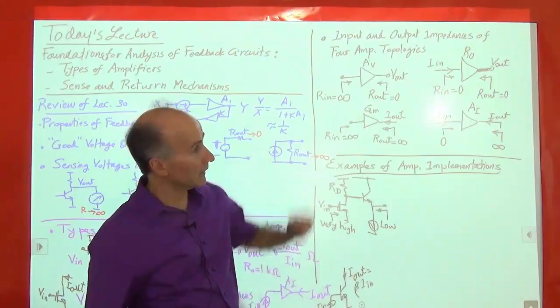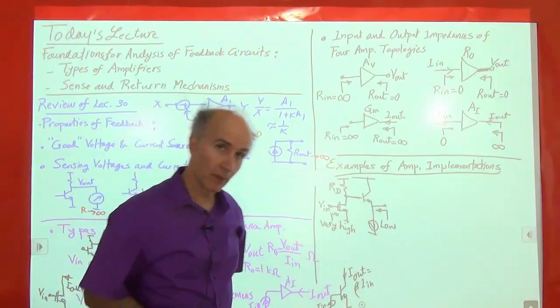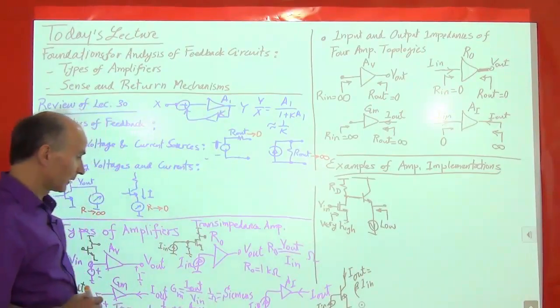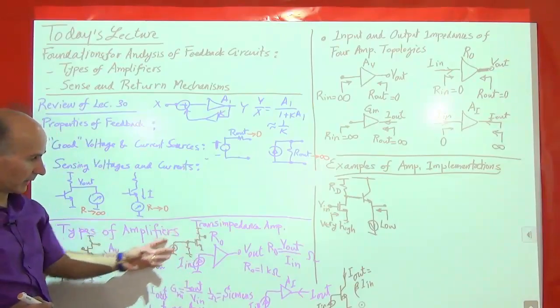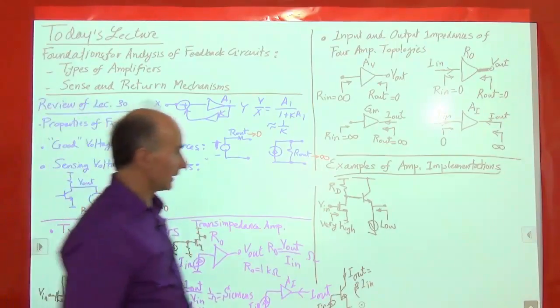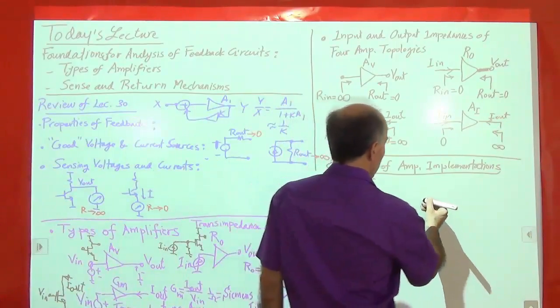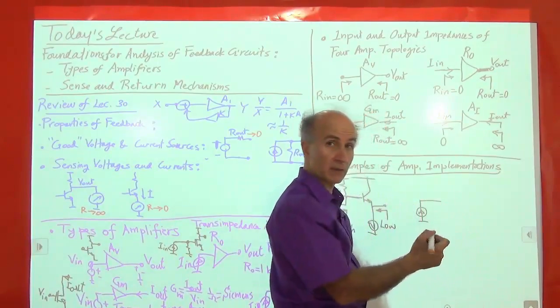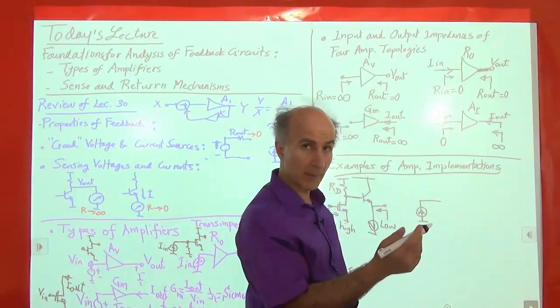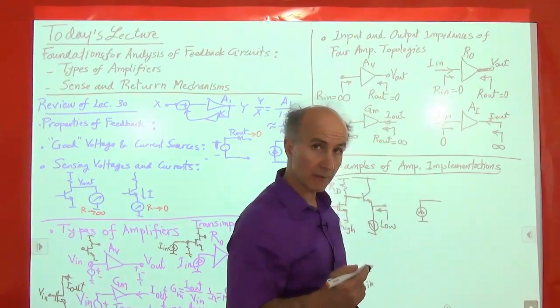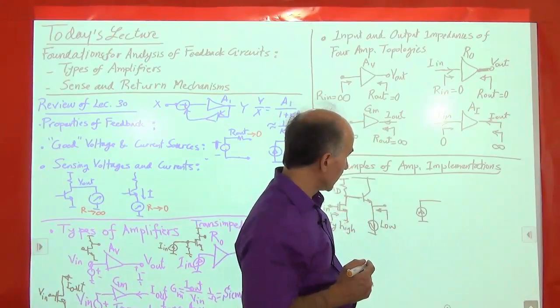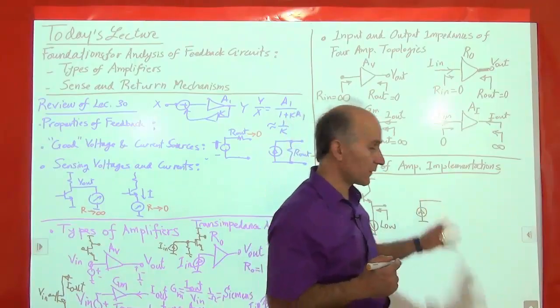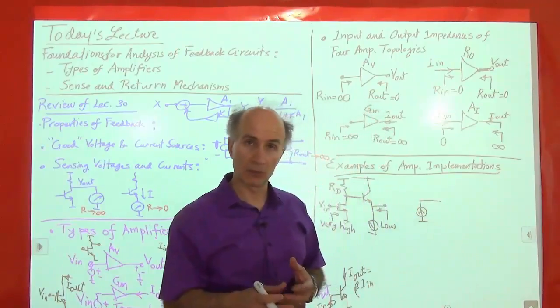All right, let's look at the transimpedance amplifier. So I said that to build a transimpedance amplifier, we can do something like this, right? So let's go ahead and do that. We have a current. The current has to flow through something, right? The current cannot see infinite impedance, preferably a low impedance. So do I know a circuit whose input impedance is low?